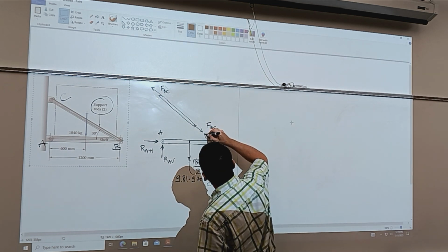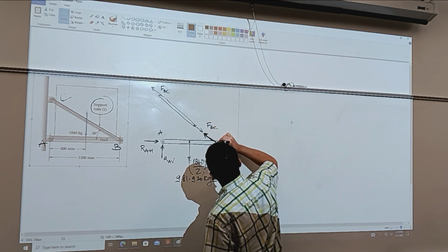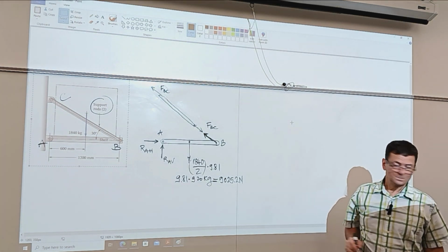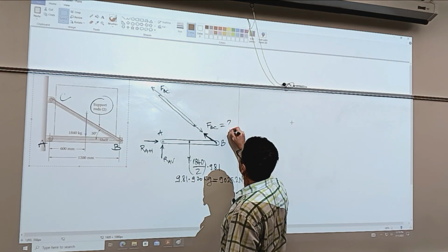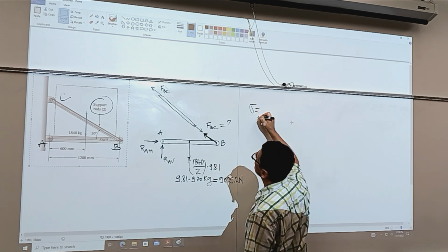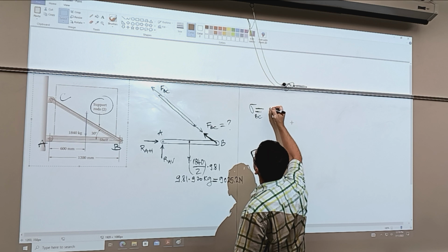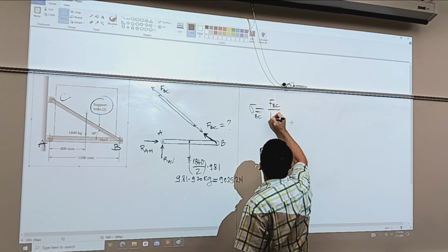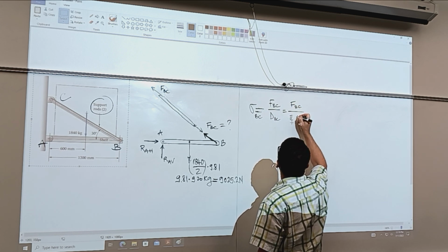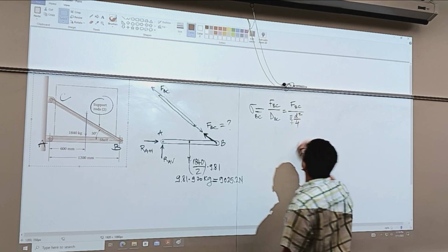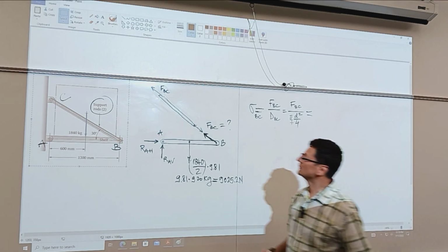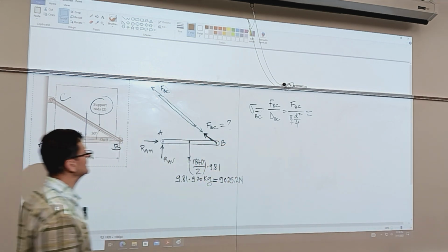Our analysis will go, because it's where the input force is given, with the shell itself. Do you follow? Okay, so this is the unknown. Once we know this, we can calculate the tensile stress in the link BC. And this is going to be FBC divided by the area, pi times diameter squared over 4. We have this already, it's 12 millimeters. We need to calculate the force. So how do we get the force FBC? Any takers?